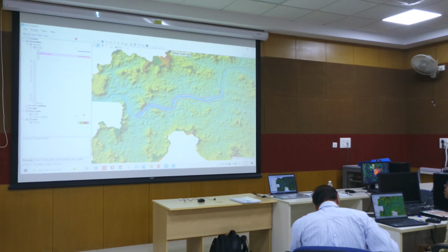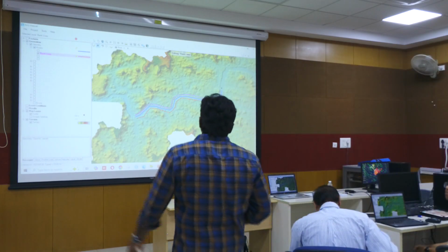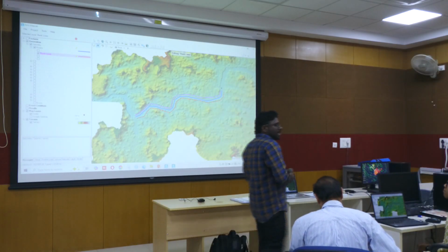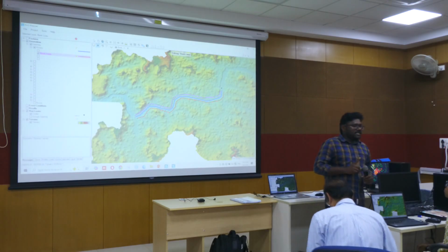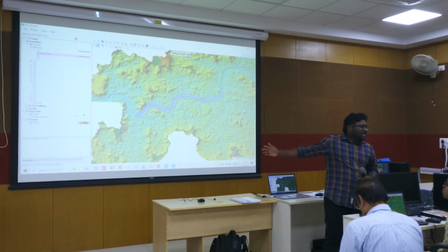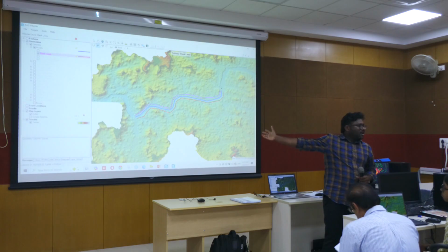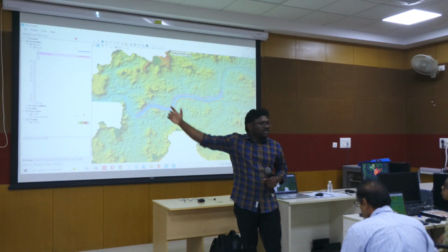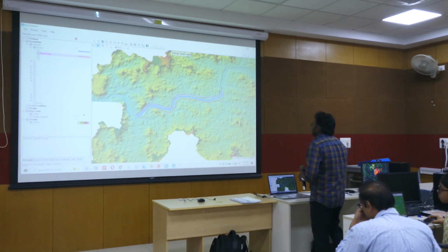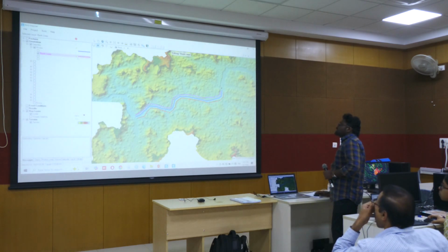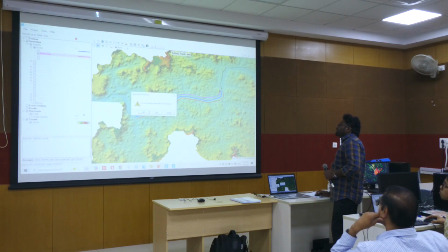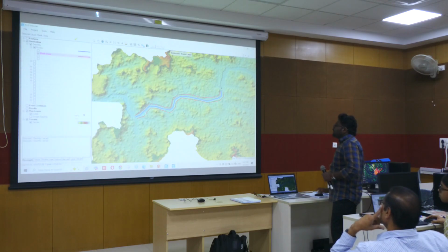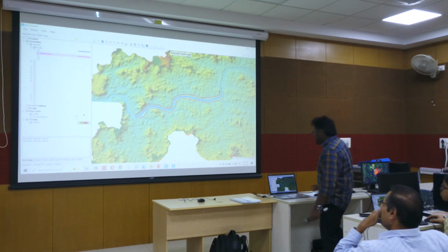All of you reach here? So our center line is done. Bank lines are done. Next, flow paths. Flow paths are nothing but lines we draw considering the floodplains. Okay? Just save these lines. Stop editing, just click save. So these lines are saved.